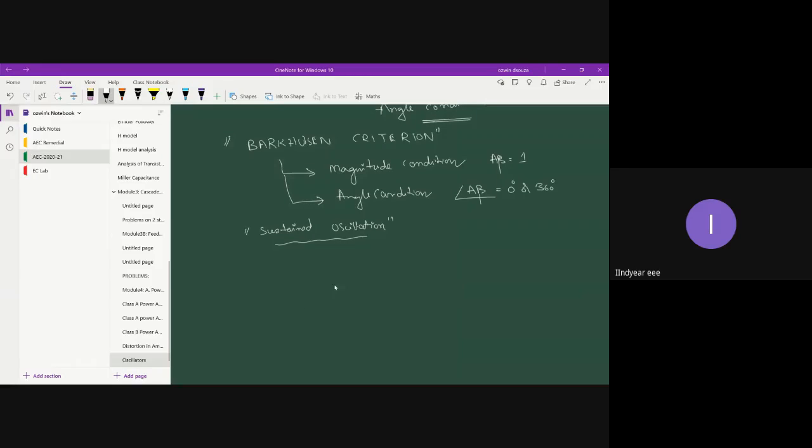In the sense, the moment the DC power supply is turned on, this is your oscillator circuit. The noise which is present in the resistor, see, a resistor is a conductor element, right? Now, in a conductor element, there are excess electrons, and these free electrons move in a random path, due to which there will be a noise signal. These noise signals are normally bidirectional in nature because their path is highly unpredictable. They move in a crazy path, so basically it is an untraceable bidirectional path. But the amplitude of the noise signal is generally in the range of microvolts. Very, very low voltage signal.